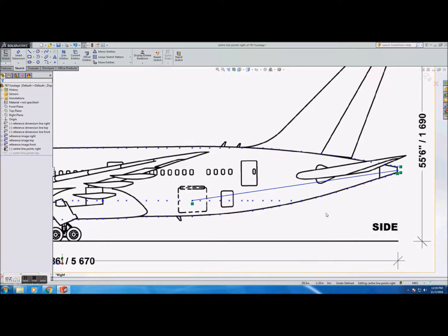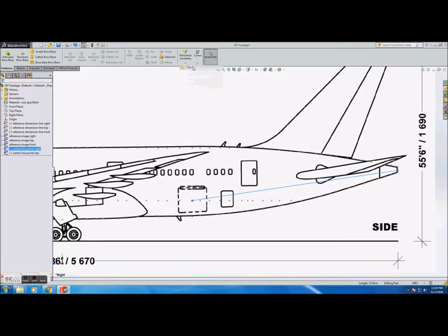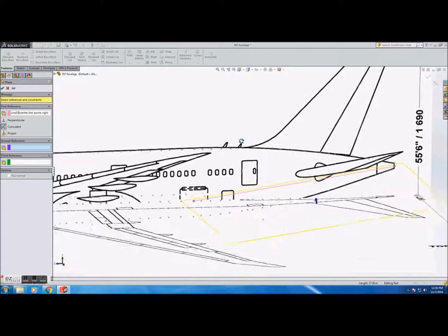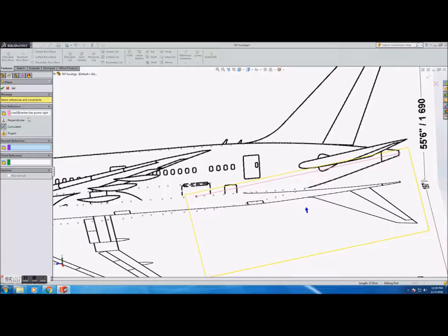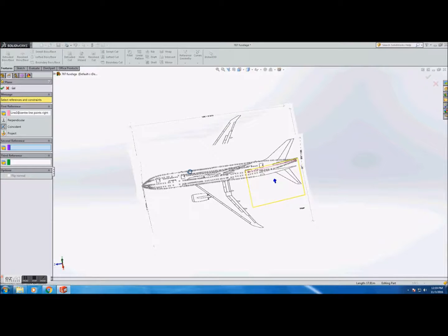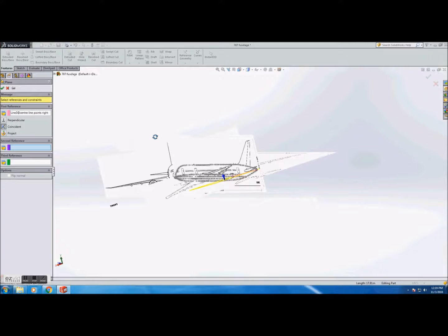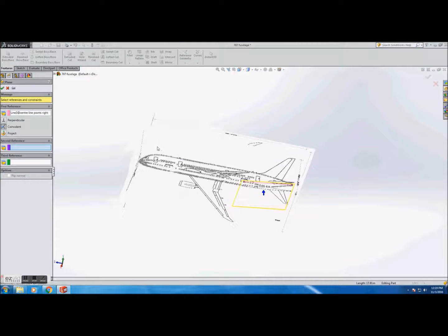And so what we're going to be doing with this line is anchoring our new plane on there, and in this plane we're going to be going over the points that we previously drew in the top plane. We're going to be reiterating them in this angled plane, and from there we're going to be able to create our profiles more easily, without the trouble that would have come about if we tried to do it just in the planes that we had existing: the top, right and front planes.